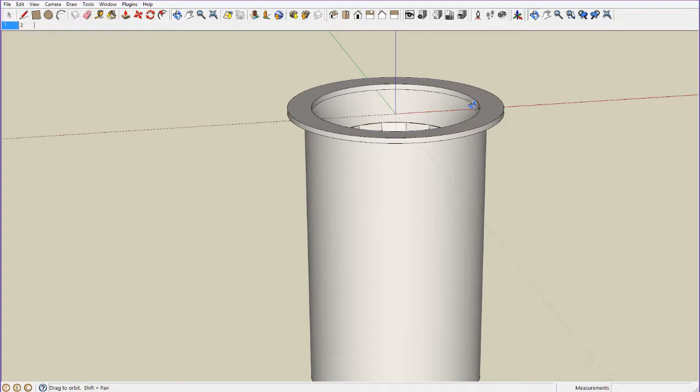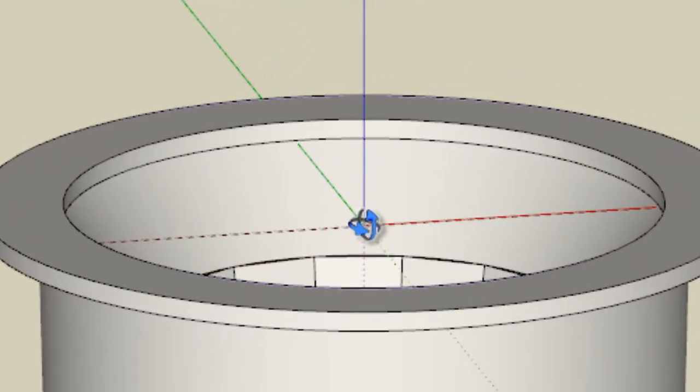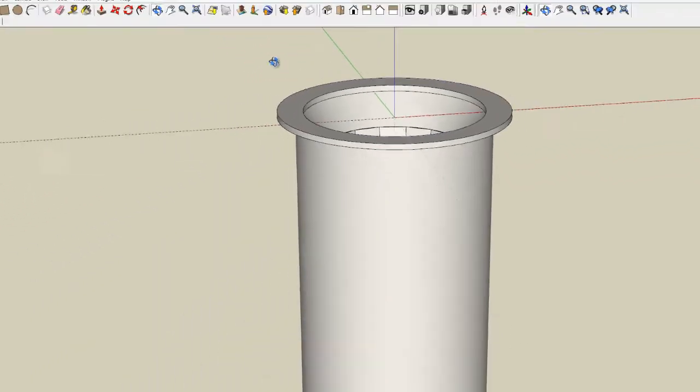Now, if the trim edge here was in line with the origin plane, that's all we need to have, and the creation of this light fitting as a component will use that trim edge to cut the ceiling. But in actual fact here, and somewhat deliberately, I've chosen something just clear of the ceiling trim so we can see a more certain way of dealing with this.